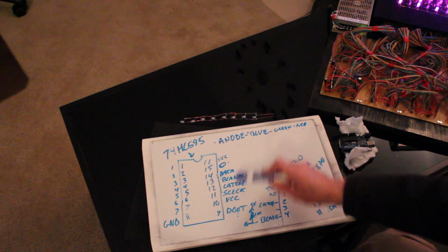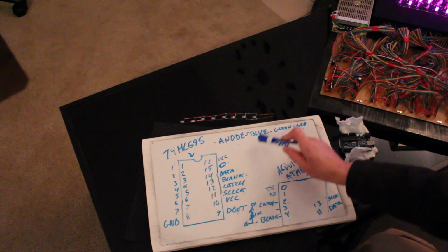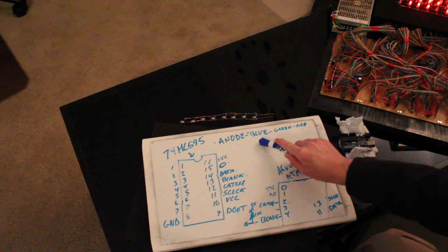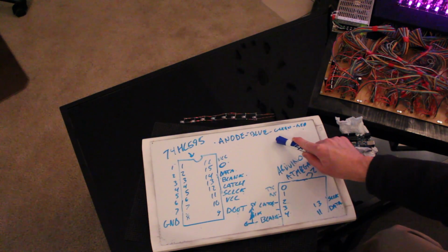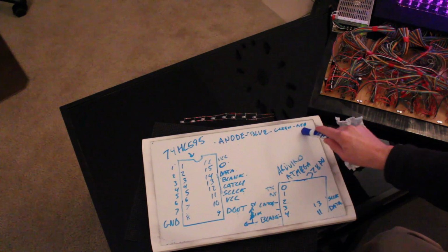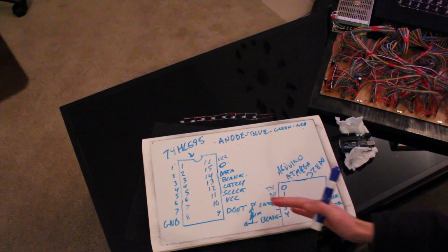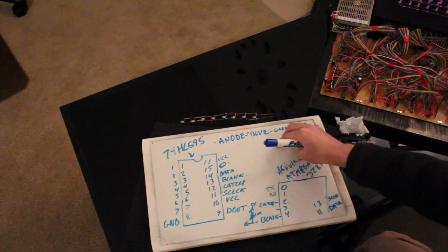It goes in, out. Here, see D out is pin 9. D out goes to the D in of the first blue shift register, and it goes through all 8 of those, then to the green, then to the red. And the way you shift the data in, it just keeps pushing it down all the way to the end.